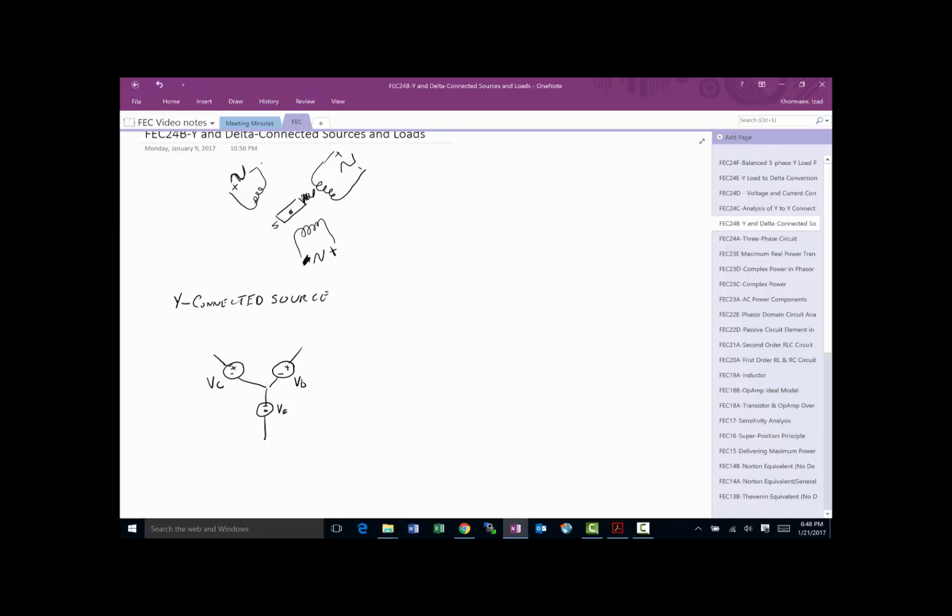Depending on what sequence you use, you end up with either a positive sequence or a negative sequence. To be complete, we also have to add what we call the generator impedance, or winding impedance. They give it all kinds of names, but let's use winding. So this is ZW equal to RW plus jXW, where R is the resistive value and X is the reactance.